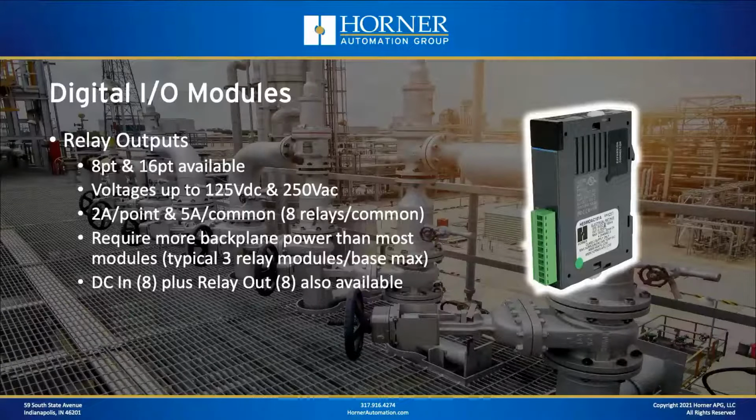Now, the relay output cards require more backplane power than almost every other module that's available for SmartRail. What that means is you'll be limited to approximately 3 relay modules per SmartRail base before you start getting low on power. Whereas just about every other type of IO module that you use won't have that sort of limitation. Also noting, we have a DC in 8-point plus relay out 8-point module available as well.